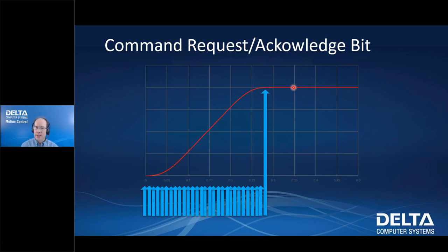There can be a little issue here with that. Let's see this green line here. Let's say that's where the PLC sends the command to the RMC. And then the yellow line, let's say that's where it starts checking for the in-position status bit. Well, there's no guarantee that in the logic, when you look for the in-position status bit, that data you're looking at actually came from after you sent the command.